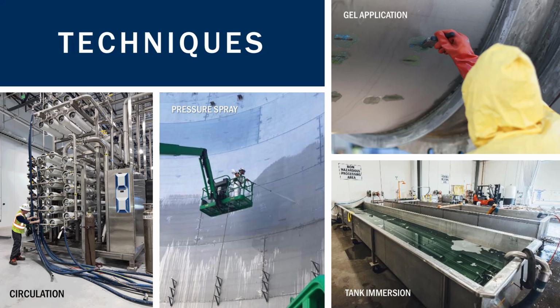If you have large components or just small spot treatments, pressure spraying or gel application works as well with passivation, because you're not going to get the temperature, but you still get the kinetic energy increase for your reaction by agitation or impingement of the pressure washer. So we actually see pretty similar chrome to iron ratios if we're scrubbing a gel into a particular spot or spraying at high velocity onto a surface to passivate.